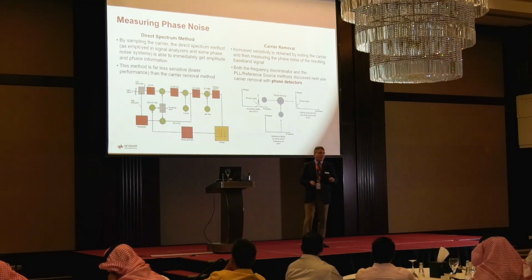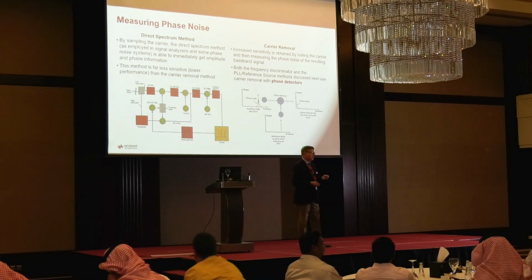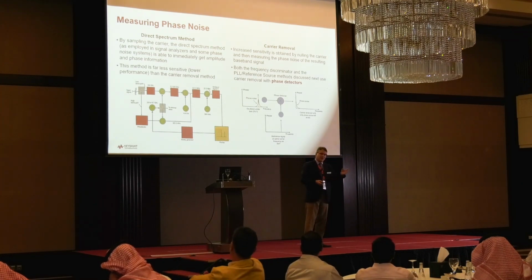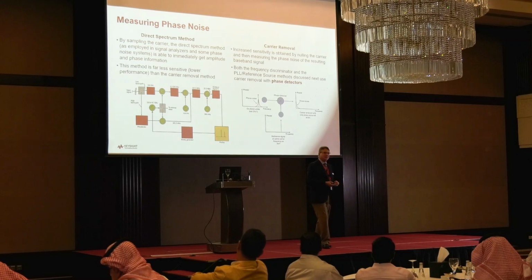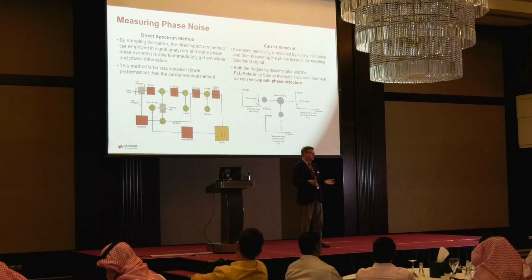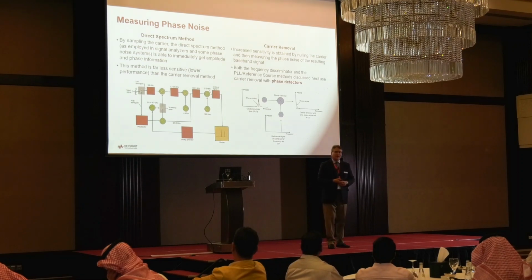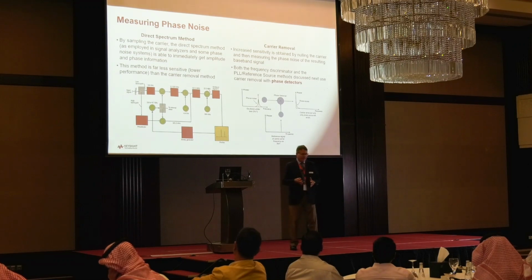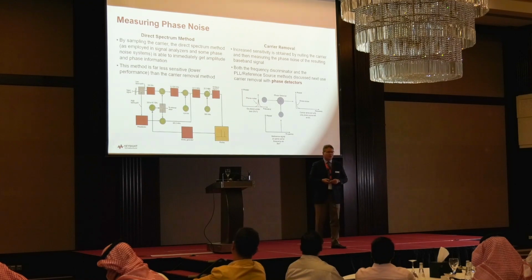The challenge or the problem with that approach, while it's easy, is it's not very sensitive. And the reason for that is if you look at all those down conversion stages, all those electronics, they are adding noise to the signal of interest. So your sensitivity, or your ability to resolve very low phase noise, is affected. So for high performance measurements, and typically that's in our world of radar, STALOs and exciters, we use a different approach. It's called the carrier removal technique.